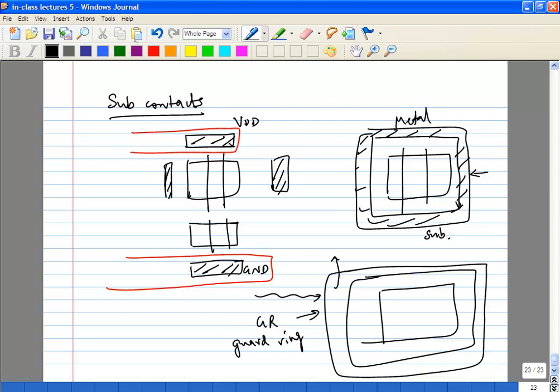And now obviously, let's say you have a guard ring and you have a substrate ring inside, okay. So remember, because these two have totally different functions, do not connect them at the end to the same ground, okay. Let's say this is your ground pad, use a separate ground pad for the substrate ring. If you end up connecting these two, it's almost the same thing as not having the guard ring, okay, because at the end of the day it is going to go out through the low impedance path and come back to the substrate directly. You understand what I'm saying, right?